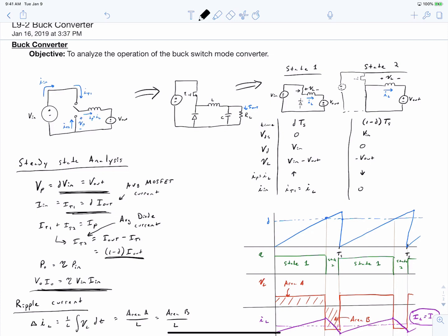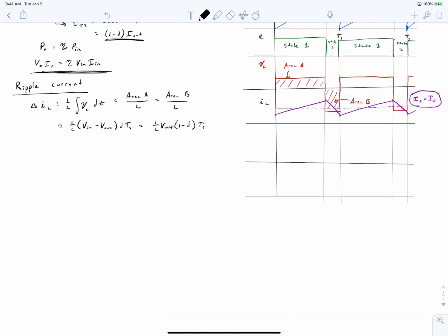And this is consistent with our approach to analyzing power electronic circuits, that we try to simplify things as much as possible to study only one portion of the circuit at a time. However, now, in order to study the capacitor current, we have to acknowledge that our load voltage actually does change. So instead of modeling our load as an equivalent voltage source, we're going to model it as an equivalent current source where the load current is DC.